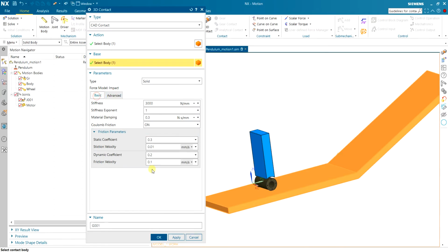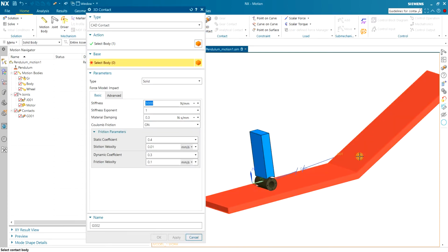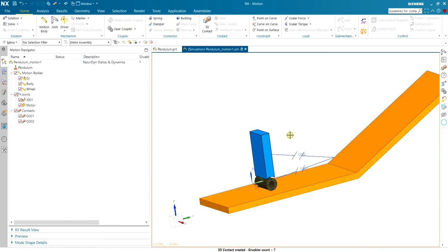Usually you don't need to change other options. I also want to have friction. I may increase the frictions both for dynamic and static to have more friction. We can also define contact between the body and the ground, even though it's not supposed to fall, but it's better for visualization. And now I can have the first run.